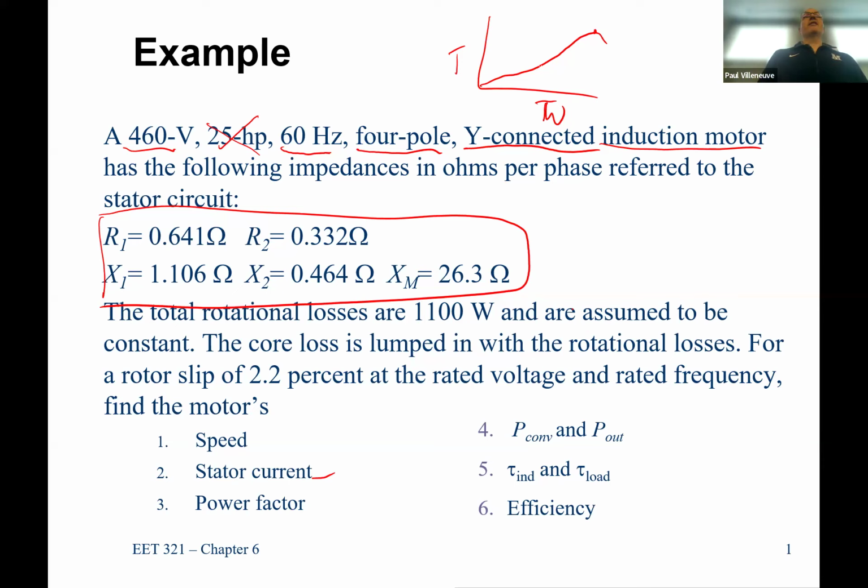Anybody know what cavitation is? It's like instant vaporization or boiling in water. Yeah, the air trapped in the water actually gets released. And what ends up happening is now you have air in your fluid. So you no longer have a homogeneous substance, you have air bubbles, which have a different density than the water. So when the pump hits water and then air and then water, it vibrates. Cavitation is a vibration as a result of running it at too high a speed. If you get above this point, you start to get cavitation, and then torque goes down because it's hitting water, then it's hitting air, and the pump won't last very long.